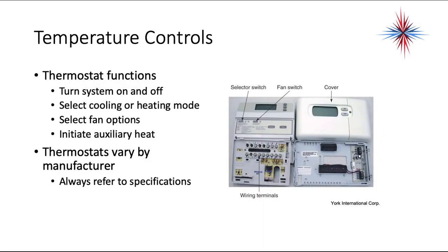Temperature controls, okay, in heat pump systems are relatively easy. The thermostat function turns the system on and off, selects a heating or cooling mode, selects fan operations, and can initiate auxiliary heat. Thermostats vary by manufacturers. Always read the directions.